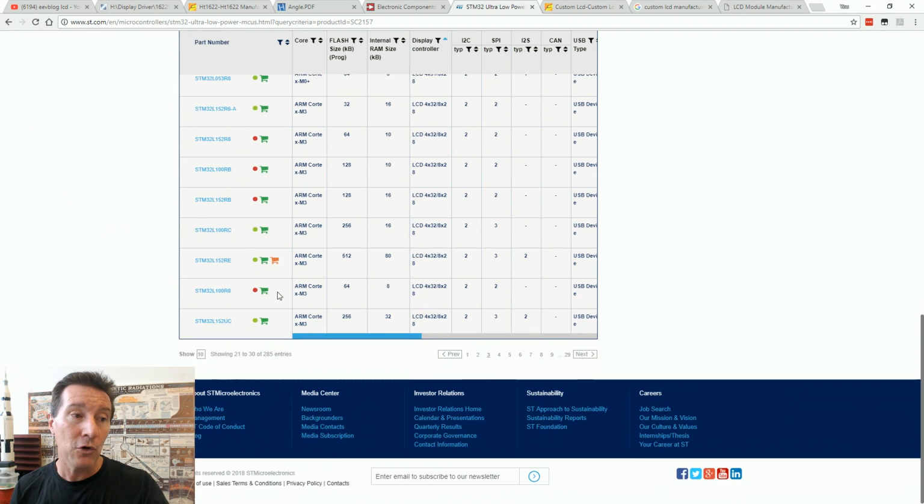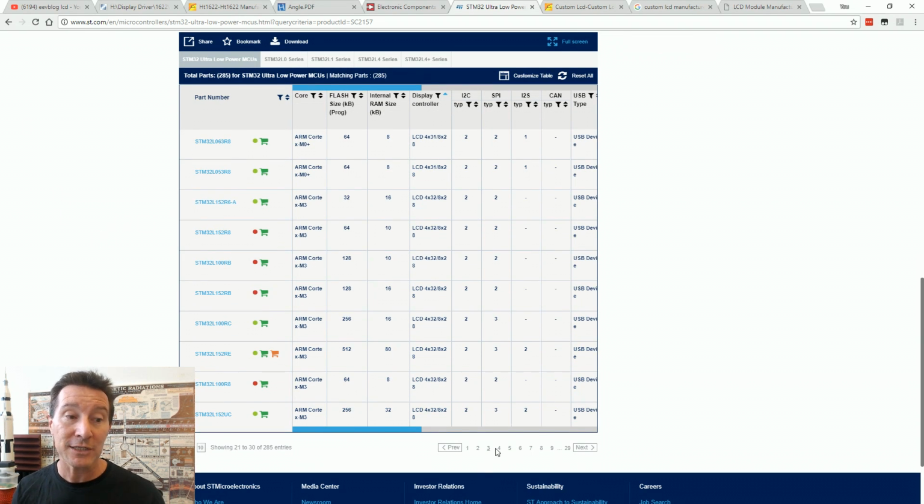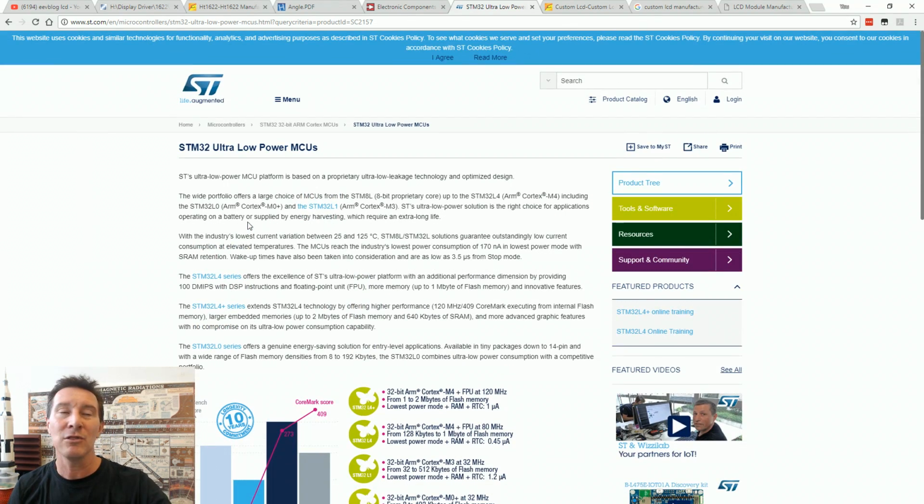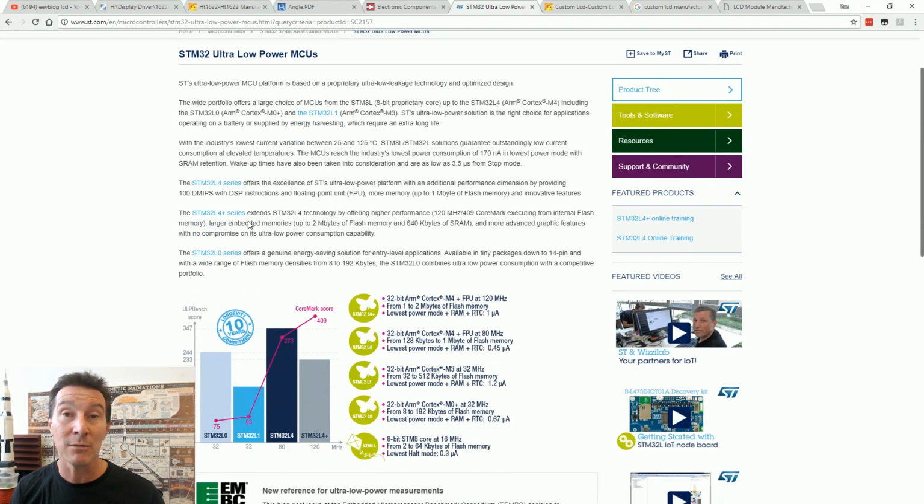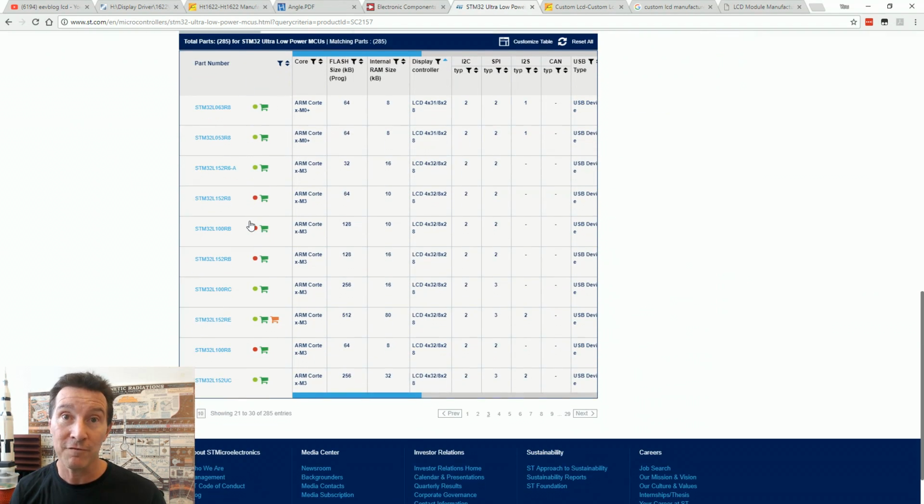And we could actually find one that did the job for us here. Any one of these 8 by 28 ones would actually do the business, and probably if you went in and saw the data sheet, you could choose a different package size to get that perhaps. And it's the same across a lot of these microcontroller manufacturers, same story effectively across them. But you know, $1.50 extra, for example, or it could be 50 cents or whatever. But if you can get a separate LCD controller for less than that, then you're ahead on your BOM cost.